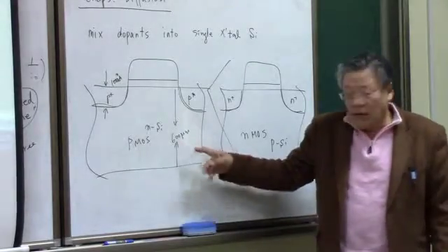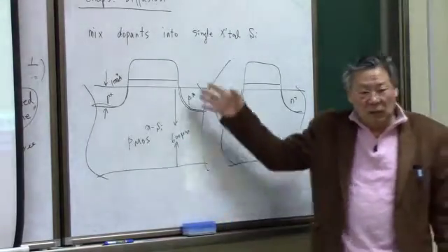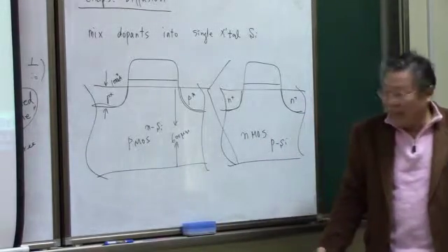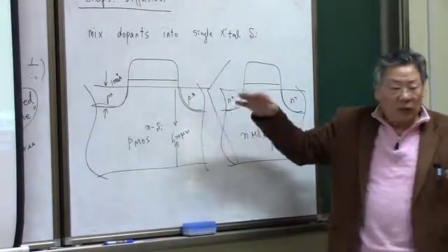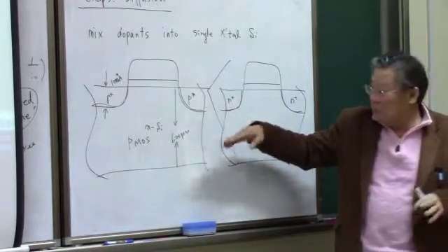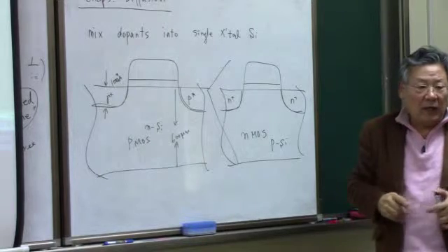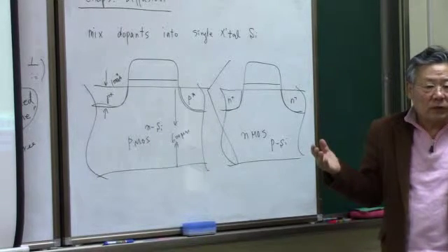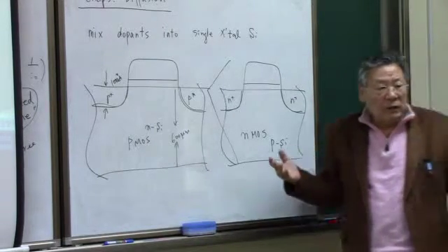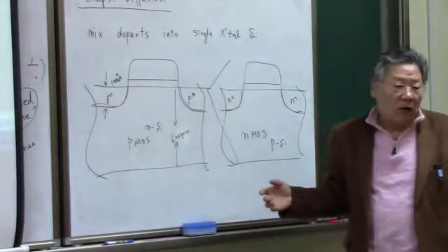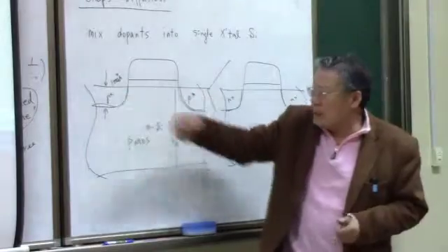This 600 microns, we cannot have this much diffused length in the solid state, okay? Just for 1,000 angstrom, we have very elevated temperatures, like above 1,000 degrees centigrade, for typically 1 or 2 hours to make a diffusion like this.